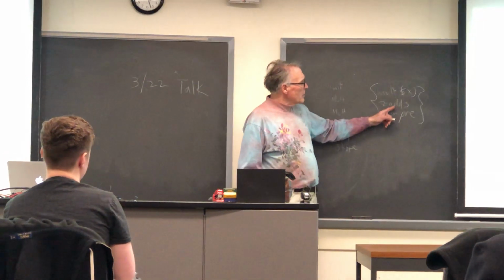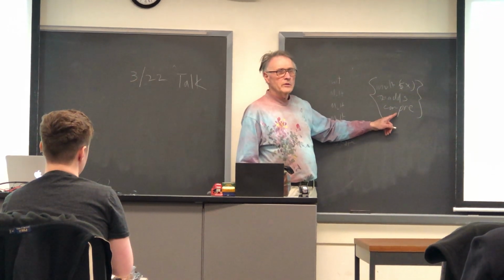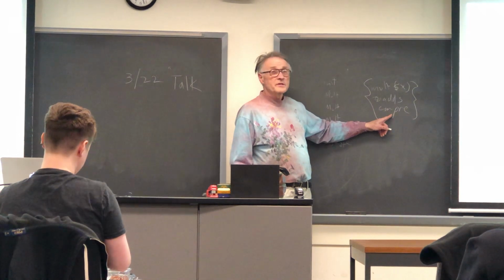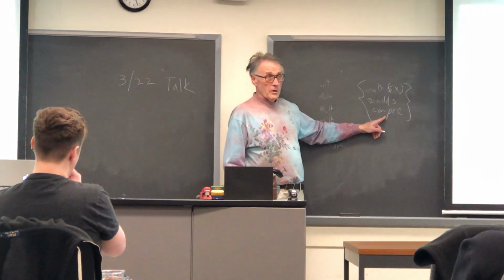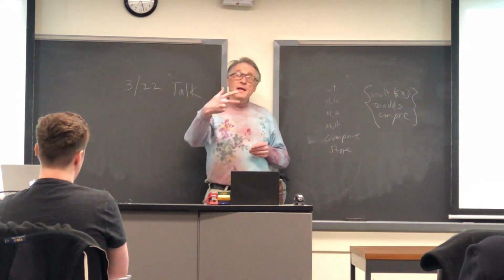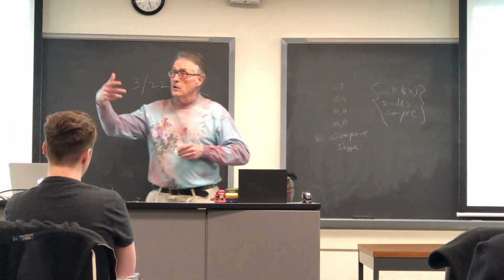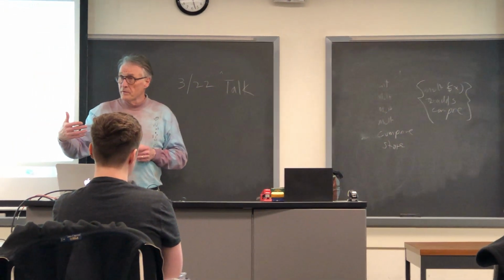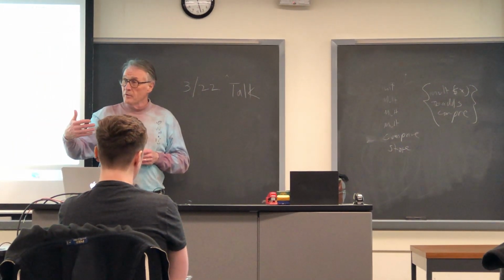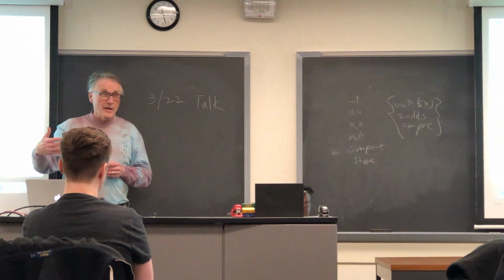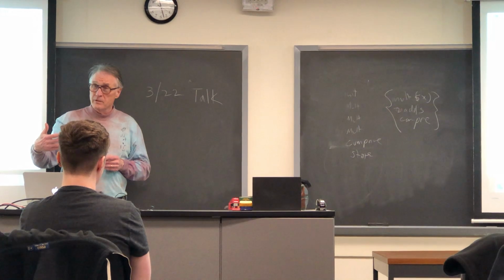Because as soon as you put all of this stuff into one clock cycle, you may have to slow down the clock. So you may have to run this at 50 megahertz or slower if you have a set of multiplies and adds and a compare which are dependent upon each other in order. You can't do them all at once. They're not independent operations. You have to do them in order. And therefore the signal has to propagate through a big chunk of logic and it will be slower.